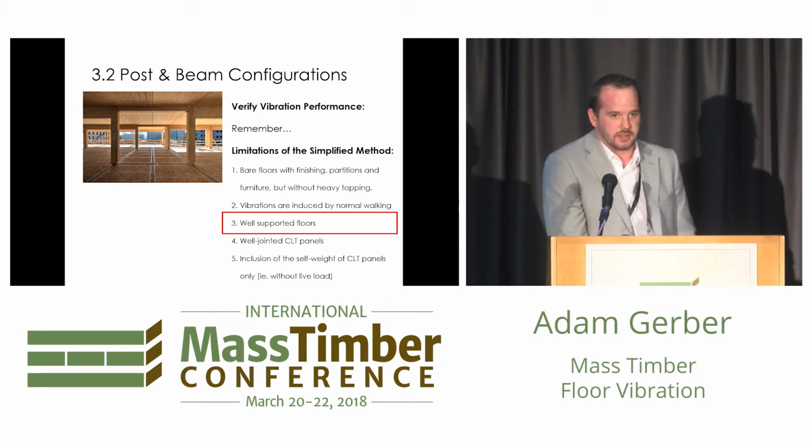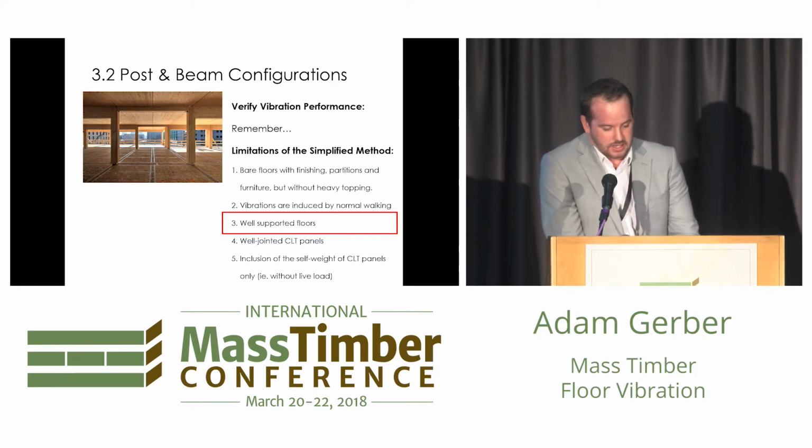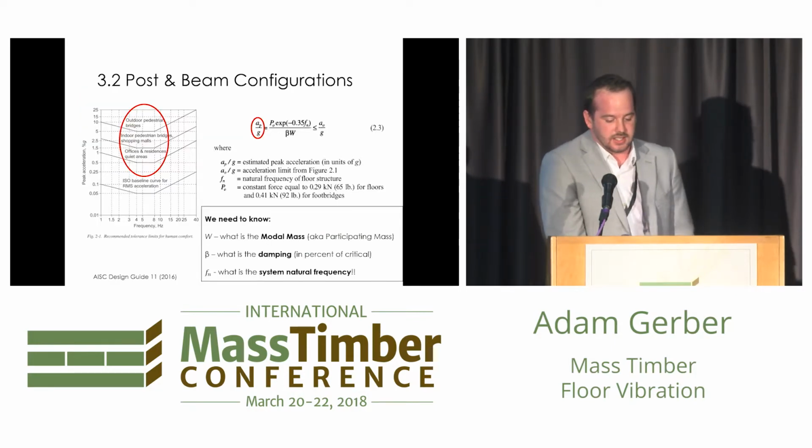So here we get into an area where we're no longer necessarily considered a well-supported floor. So if we take the Design Guide 11 approach and we go through and we calculate or try and predict the peak accelerations due to walking, what do we need to know? We need to know something about the mass, we need to know something about the damping, and what is the total system natural frequency.